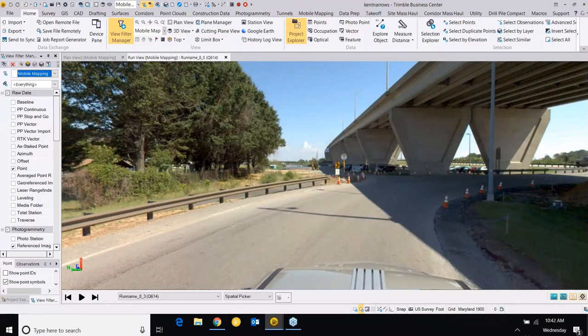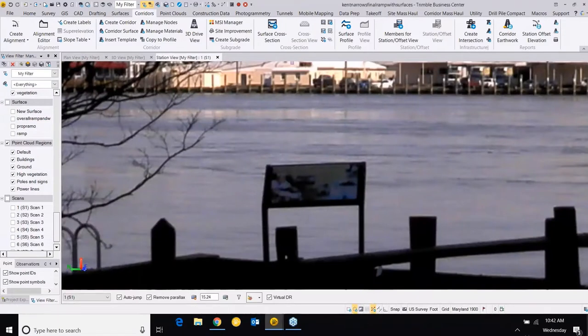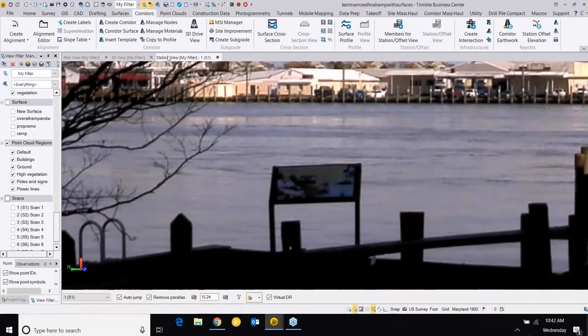So from just driving by in that parking lot, you can only do 15 miles an hour. So driving by at 15 miles an hour, 500ths of an inch off of all my shots that were tied in to the RTK network. And I think that is pretty good when you're looking for a software that can do all of those things in one.